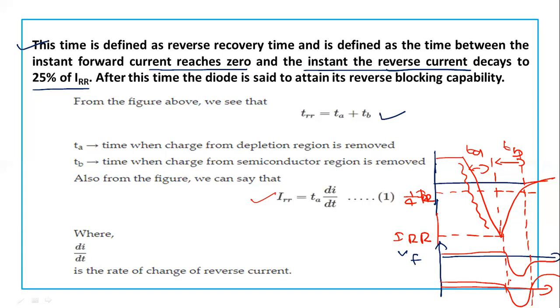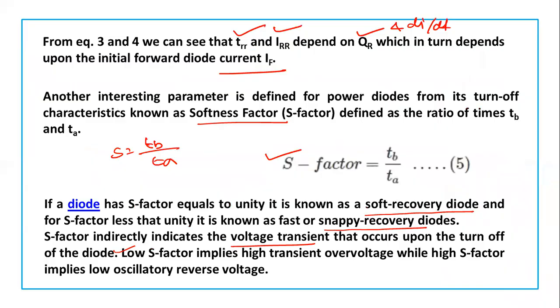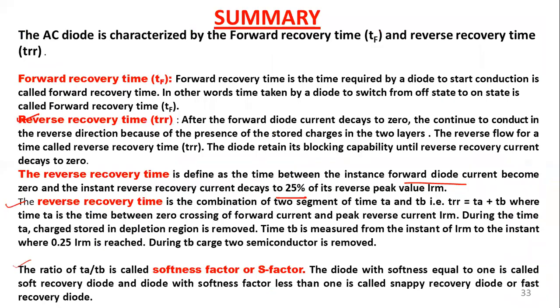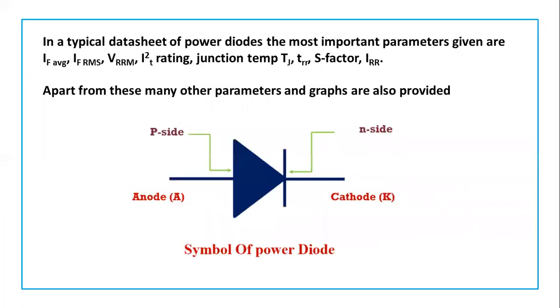We have seen that power diodes take a finite time to switch on, and to remove the space charge in the depletion region by a large reverse bias voltage during turn off. During turn off, the excess carriers in the drift region have to be removed first before the metallurgical junction gets reverse biased. The removal of these excess carriers can be done by recombination or by sweep out of reverse diode current. Just common things I have explained.